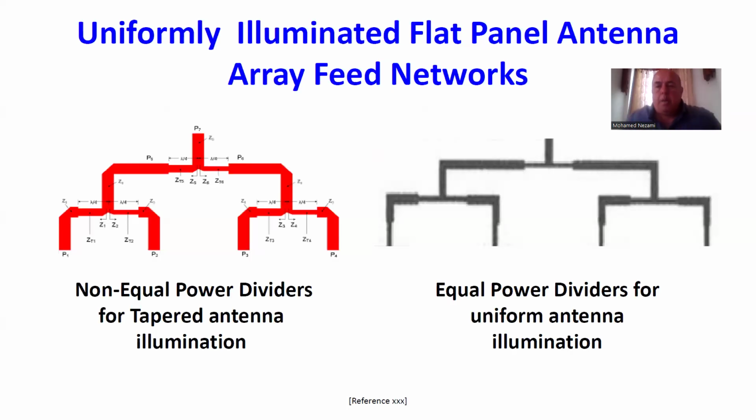And it can be two types. It can be uniform, dividing the signal so that it's delivered uniformly to every patch, like in this example, where we have 4 antenna elements, an array of 4. Or it could be unequal. This is unequal in here. This is a T-junction that does unequal splitting. And we will show the principle of this, how it works, and the design equations for this, okay?